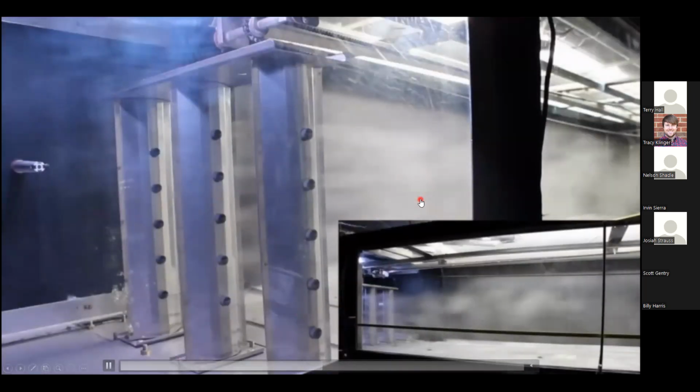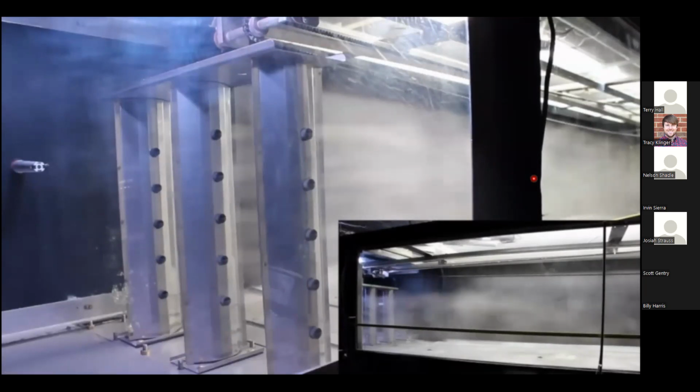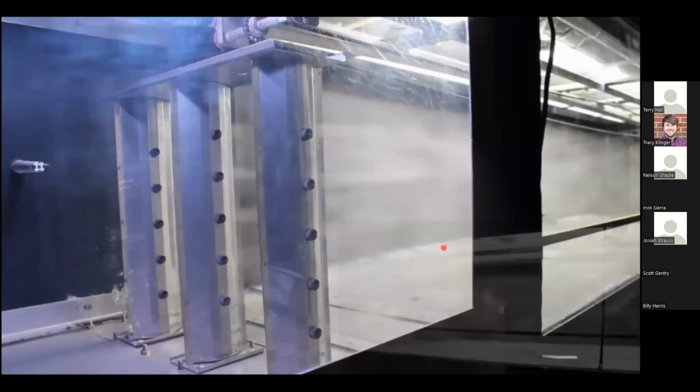This is the area where you want to keep, if you have a high limit for the humidifier, we usually recommend 15 feet plus downstream of the dispersion grid. This is why if you start producing steam and your vapor trail is this long, it'll trip off the high limit, and then you'll go into an on-off cycle.